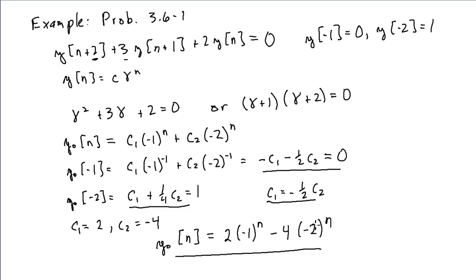You might ask yourself too, in comparing this to continuous time systems, is this a stable system? Looking at the output for these initial conditions, is the output growing or not? Again, the answer is slightly different than you might expect in comparison to a continuous time system. For a continuous time system, with the roots both negative, that would correspond to a stable system. That turns out not to be the case here. There's another condition that the roots have to satisfy for discrete time systems, and so we'll take a look at that in the future.